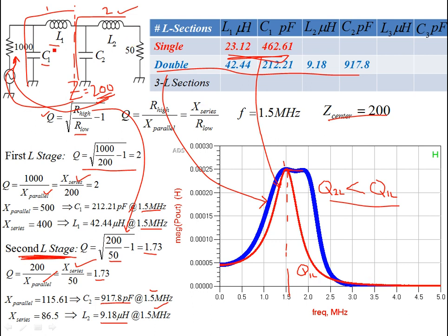Because inductors are open, capacitors are short, so there is no... At low frequencies, near DC, basically you have 1000 across 50. Because those inductors are short and capacitors are open, the capacitors won't matter, and the inductors are short, so at DC you don't have any inductive reactance, so there's a mismatch.